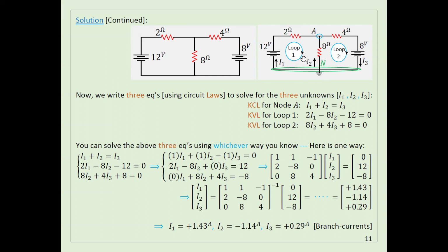Okay, if you didn't understand it well, I'm gonna repeat it again, but for this loop here, because it's almost the same thing. I will apply it here to get another equation. Very simple. The voltage here plus the voltage here plus the voltage here is equal to 0, but we need to look at polarity. The direction of this loop here is encountering the positive first. That's why this one should be positive. That's why I added here positive.